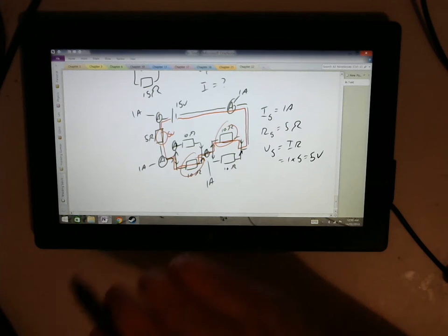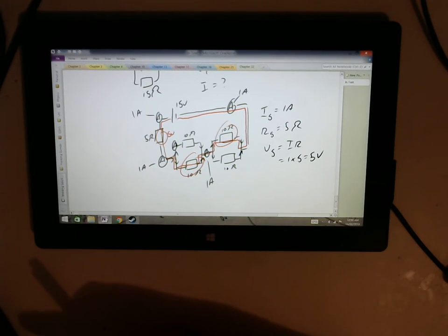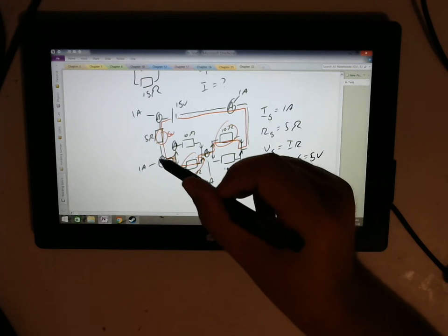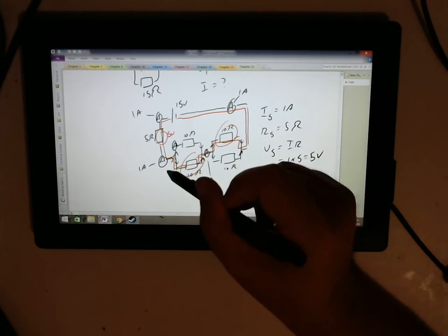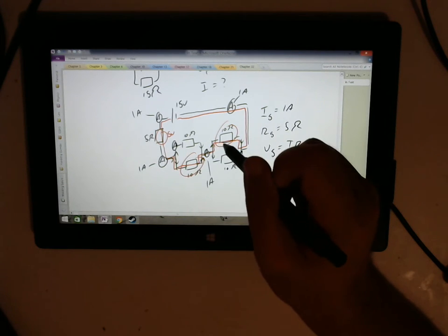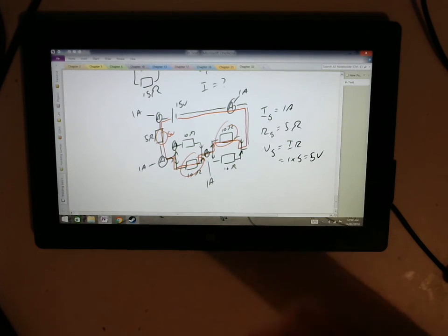Voltages in parallel are always the same. Okay? Currents in parallel are not always the same. They might be different depending on what the resistance is, but the voltage will be the same. The current is heading out, it's getting pushed at these two things with the same amount of push. The amount that goes through might end up being different, but the push is the same.